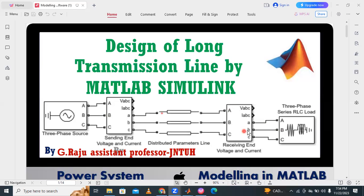And similarly, on the receiving end side, one voltage and current measurement, VI measurement, is required. That is called VABC, IABC. So this is for the receiving end side. And at this receiving end side, we have to take a three-phase series RLC load. In this three-phase RLC load, by changing it, it is possible to get RL or R or any type of load. This is called the three-phase series RLC load.